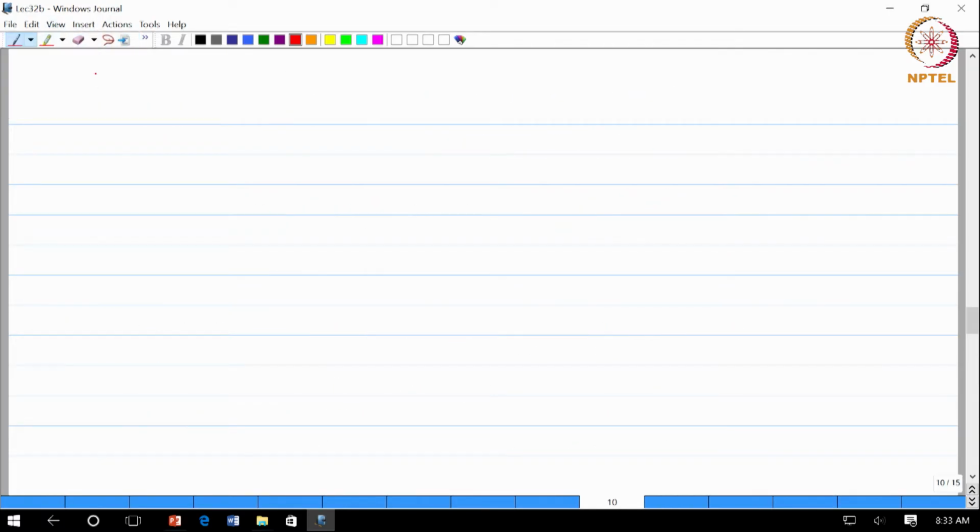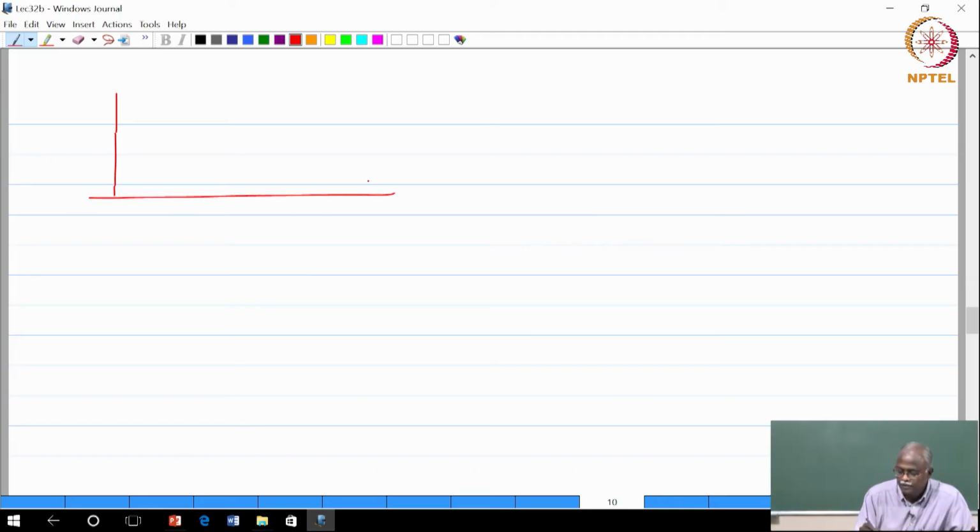So, today what we are doing for water filling is this, am I right? You are dividing the channel into subbands, or your signal into subbands, and you are assuming that the signals are orthogonal, but what will it be in practice?